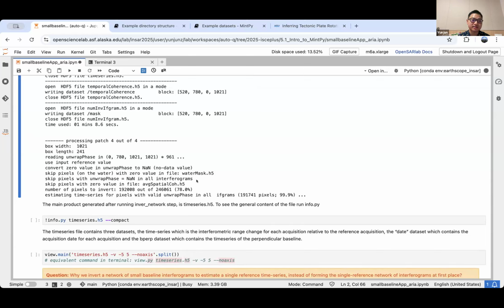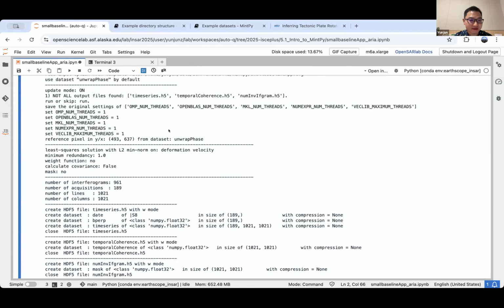From my personal experience, there is only one scenario in the last many years where weighted SBAS is not working. In all the rest, weighted inversion is always better than the non-weighted one, but the improvement is not significant. So I always use it at the very end. In all the previous analysis, where I need to rerun the dataset and update my configuration, I usually just turn the weighting off.